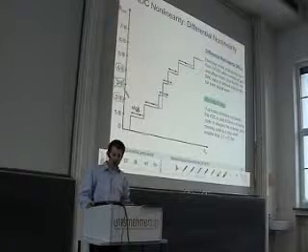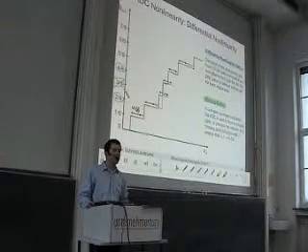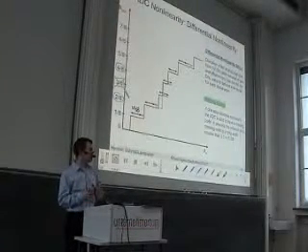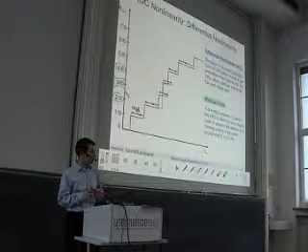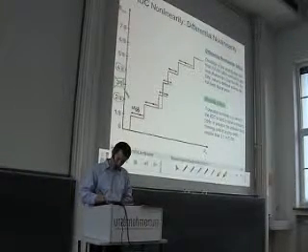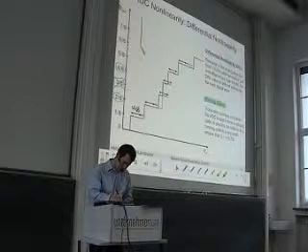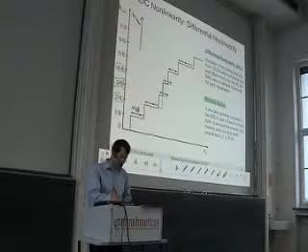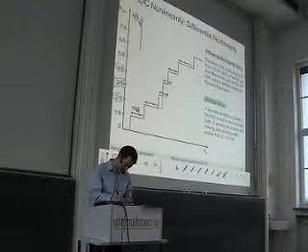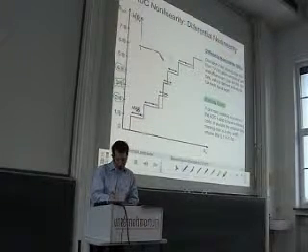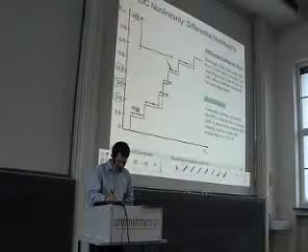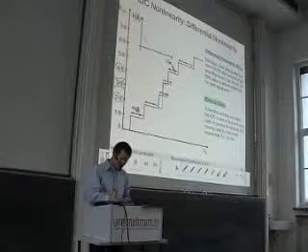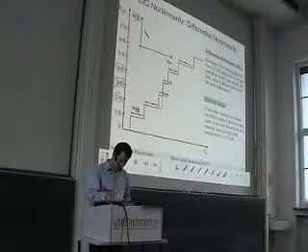One measurement that you can do to identify missing codes is to simply put noise or a random signal to the input of your ADC. Okay? Then you can say, I have a plot where I put the probability of getting a certain value, so a histogram, and on the x-axis I put all possible input voltages, V_in. And then in the ideal case you should get something like this.